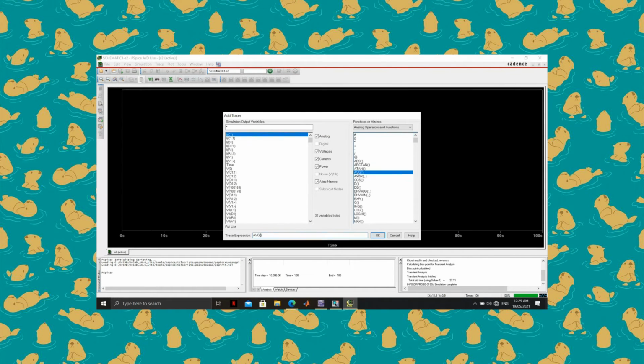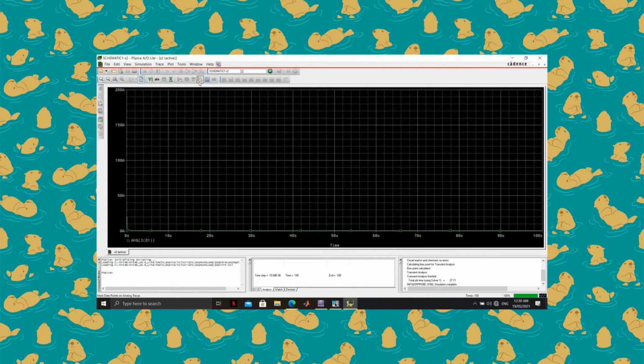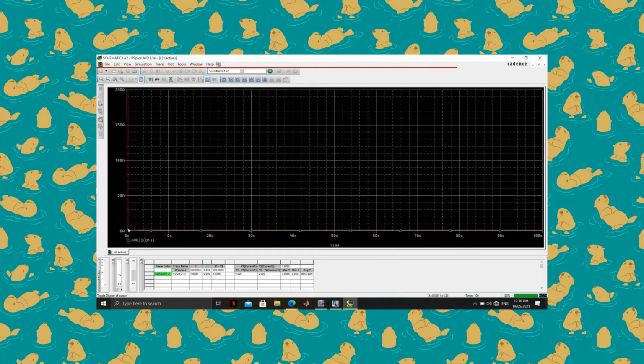Then check the average diode current. There, we could see that first it has an offset. If you look at the values at Y1, the average current value decreases over time. Therefore, we should not measure after one period since it is not yet steady. Around the 60-second point, the average current is observed to be steady in value.